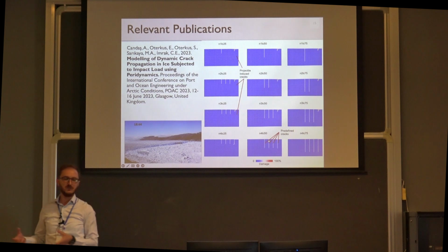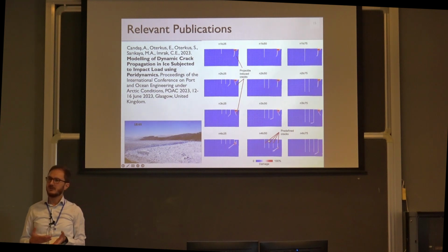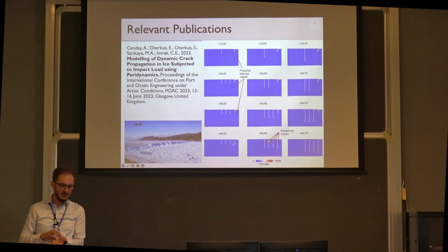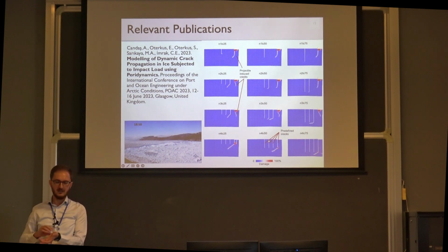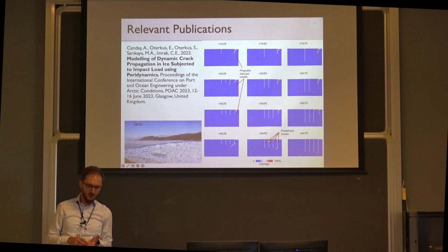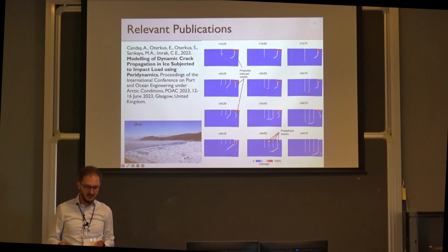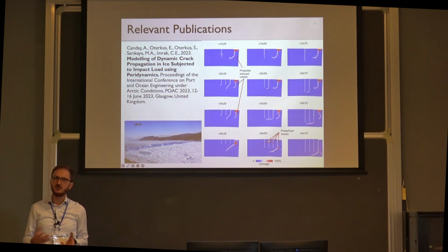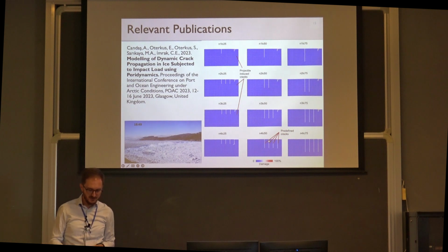When the glacier comes to the ocean, a huge part of the glacier from the terminus can separate from the main body and go into the ocean. And we use a linear elastic brittle model approach using peridynamics to model this calving process.